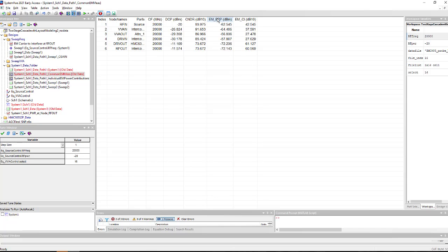And we can look at this estimated packaged power as an absolute value, or we can look at the contributions relative to the desired channel power and calculate a ratio, or carrier to interference ratio. And we can see here in the carrier to interference ratio, we have a pretty poor value on the midpoints here around the VVA out, the driver input. Those seem to be the biggest problem areas for this design.